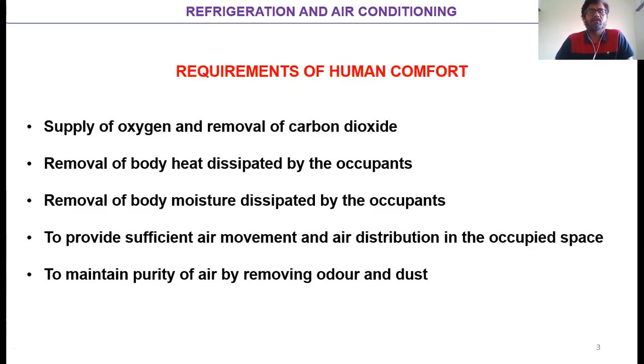Along with that, the purity of the air should also be maintained, because the air may contain some bad odor or smell, especially smoke, then dust, bacteria, and viruses, the undesirable ingredients. All those must be removed before the air is admitted to the conditioned space. So we can say that all these are very important, vital parameters as far as the comfort of the human being is concerned.